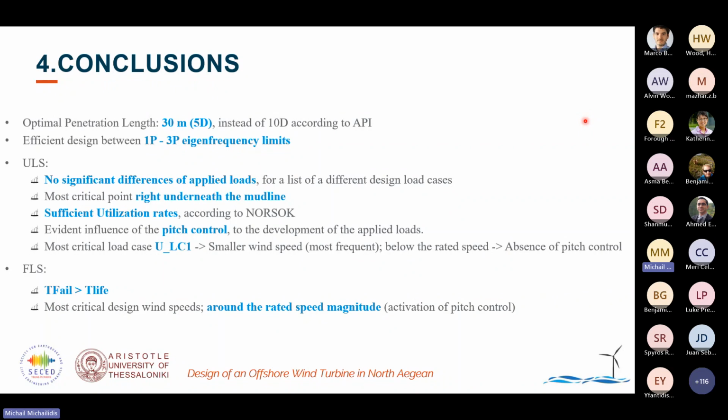The most critical structural point has been identified right underneath the mud line. There are sufficient utilization rates according to the NORSOK regulations, while there is evident influence of the pitch control on the development of the applied loads.